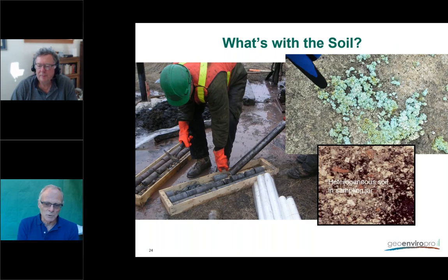The original sample was low in PAHs, and the duplicate was much higher. What we discovered, when we inspected the jar, was that it was actually asphalt particles in the sand and gravel. So then we understood why it was variable, and we were able to deal with it.